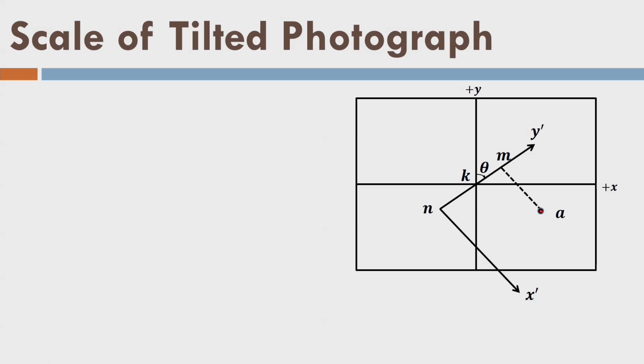So, I am measuring this point A here in the image coordinate system, what I call x y, but I know that I should measure this in the x dash y dash system, which is at angle theta, because if this is the principal line shown like this, its angle is theta with respect to the y axis. So, I can write here that these are the desired coordinates y dash and x dash, because x dash is measured along this axis x dash and y dash is measured along the y dash axis here, and this is the principal line.